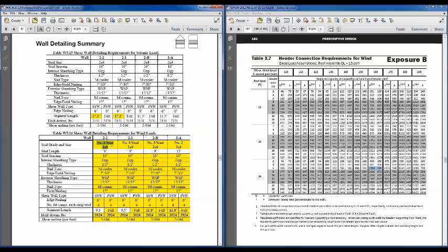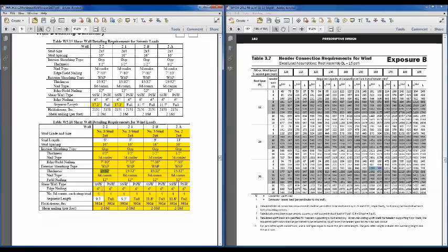So we're using number 3 in stud 2x6s at 16 inches on center, and we've got that 1/2-inch gypsum on the interior. We've got 15/32 wood structural panels on the exterior. I'm showing you both the segmented shear wall and the perforated shear wall requirements there.